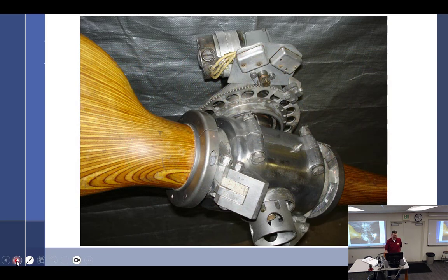We have the 2-position. This is an adjustable propeller. It is not constant speed, it's adjustable. So while you're flying along, and we'll get into this, this one has a little motor, and you have a little toggle switch, you just toggle it, and it runs a motor, and it'll just put in more pitch or less pitch. Once it's there, it's there. That's what I was talking about. Yeah. So adjustable.